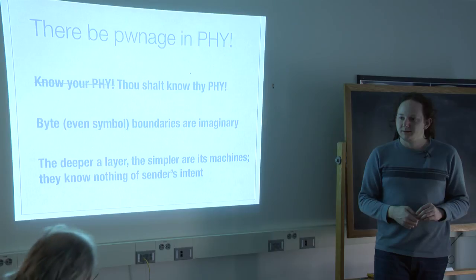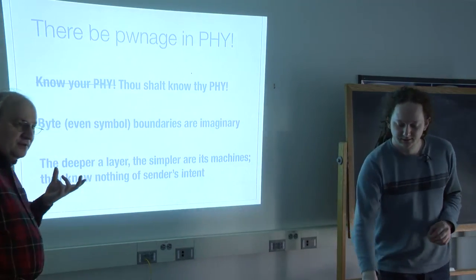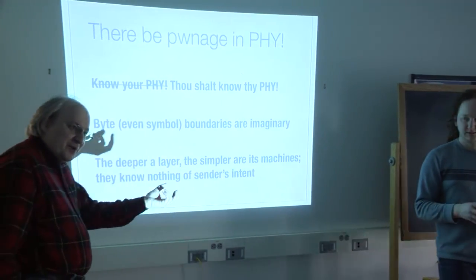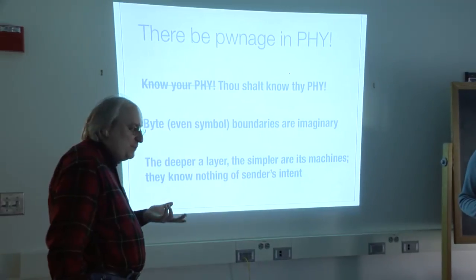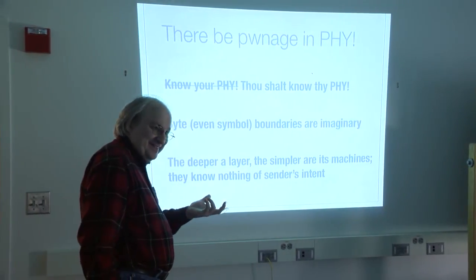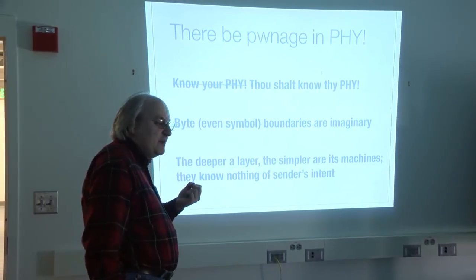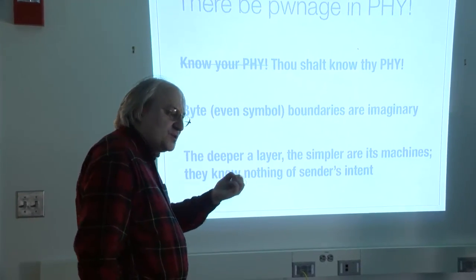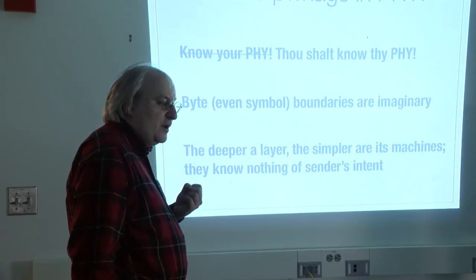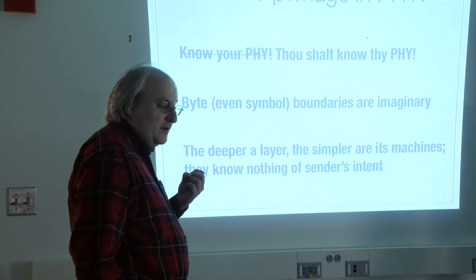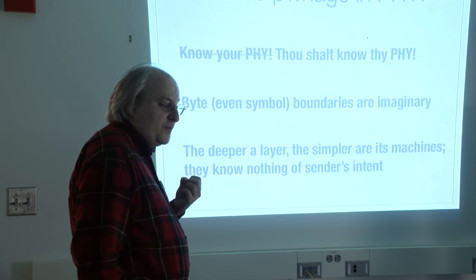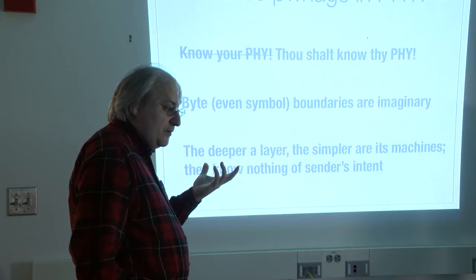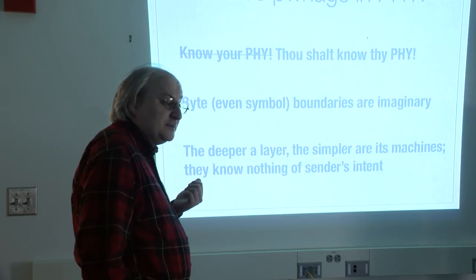Which actually means moving the SFD matching to the chip layer, perhaps, because as it happens, it's done on the symbol layer. And by that time, your error correction logic has already done its work, replacing your misaligned symbols with your actual ones.